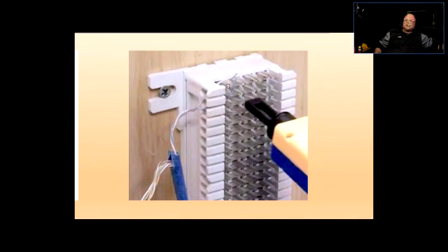What it looks like over here, these are the IDC connectors. Right? So this is 25 pair. Each conductor has its own row. So a pair of that, blue and white blue, for example, this would be a white blue row, and this would be the solid blue row. And the next one would be white orange row, and a solid orange row.